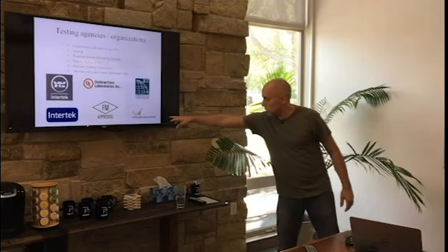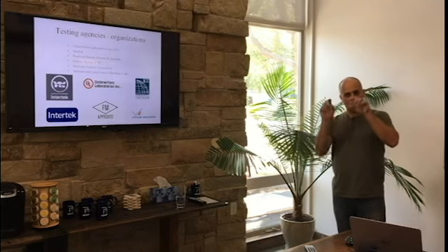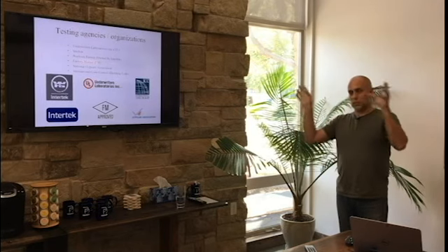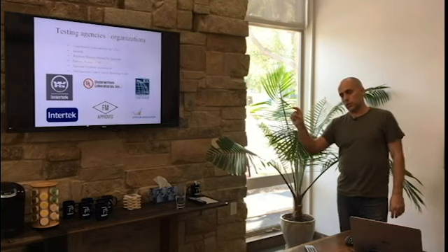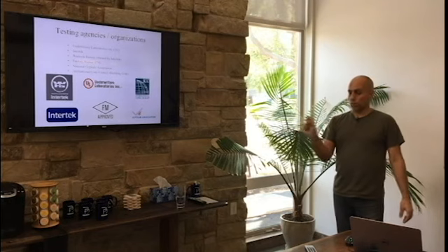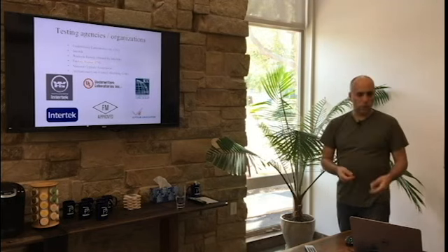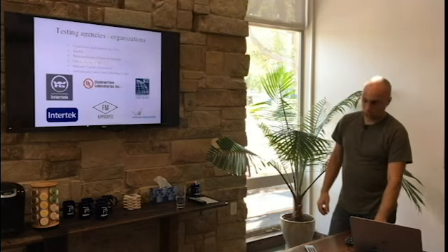If you go into the Gypsum Association's Fire Resistance Design Manual, you'll see under each of their GA, RC 2602, whatever, it'll list the various tests, whether it was a Factory Mutual test that was done in 1979, or they'll reference a UL assembly. So they're really sort of copying the two, and I'll take some questions after we're all done.